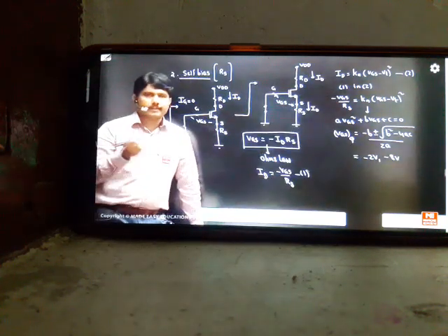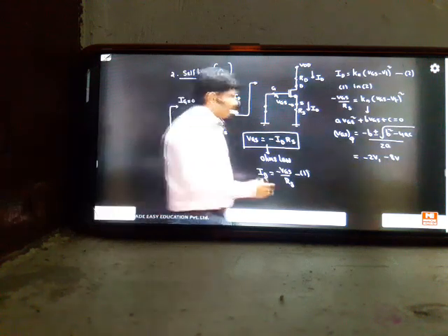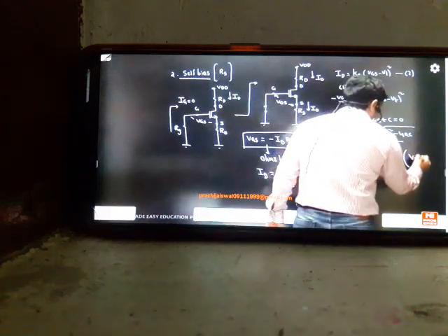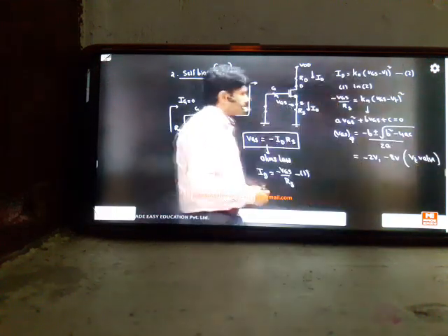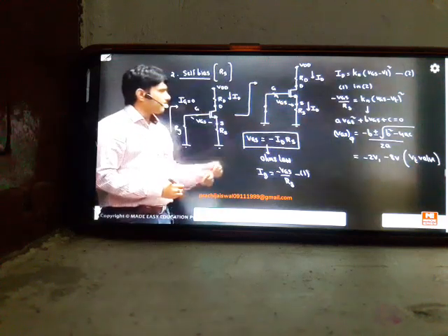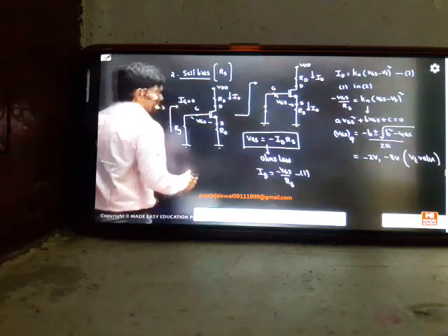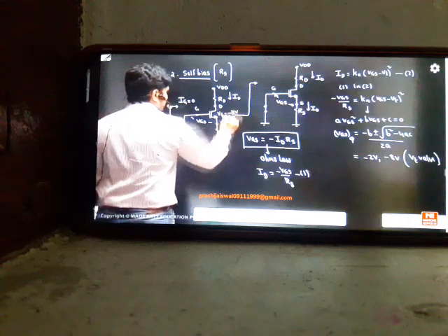Then minus 2, minus 8, which is the correct answer? How to justify? For that, the simple knowledge is to confirm the pinch-off voltage, confirm the threshold value. For example, in this problem, suppose the threshold value for this question is minus 3 volts.